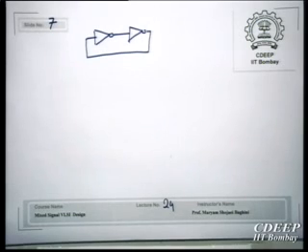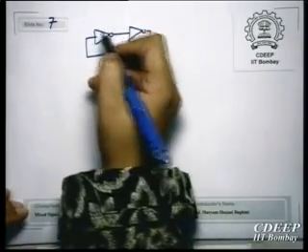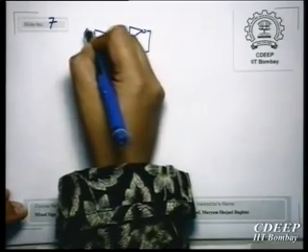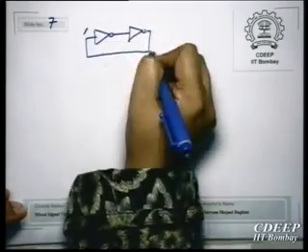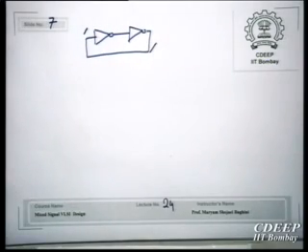The reason is its gain is very high. Therefore, it's too high to oscillate. And its actual oscillating frequency is very low. It's almost zero. Therefore, it behaves like a latch. What happens is that if you have a small change here, this change now will get amplified here. So still it is unstable. It's not a stable loop. However, it will be pushed into one of the two extreme cases, because effectively it's oscillating at zero frequency. Right.